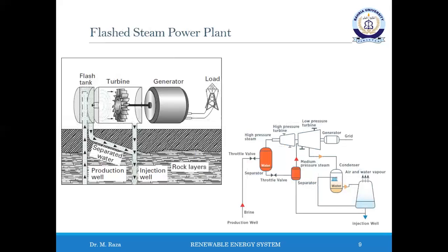The boiling point of water increases with pressure. Thus, if geothermal fluid is drawn from a deep aquifer where it is present as liquid water, it may boil on the way to the surface as the pressure is reduced. The process of steam production associated with pressure reduction is called flashing. The steam may arrive at the surface as wet steam containing droplets of water, and steam must first be separated from this water in the plant.